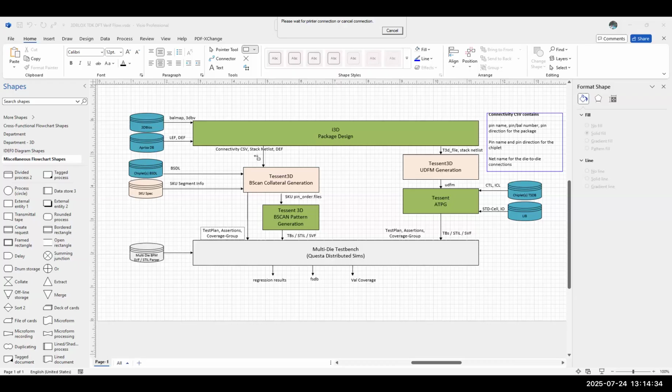Okay. So the way I think we should think about this, and I'm open to discussion, is how you do this BSDL in the DFT flow. You need some information about the chiplets, right? If you're designing the whole thing and you're doing the DFT insertion of every chip, then the tools can support that. It's kind of like a hierarchical design.